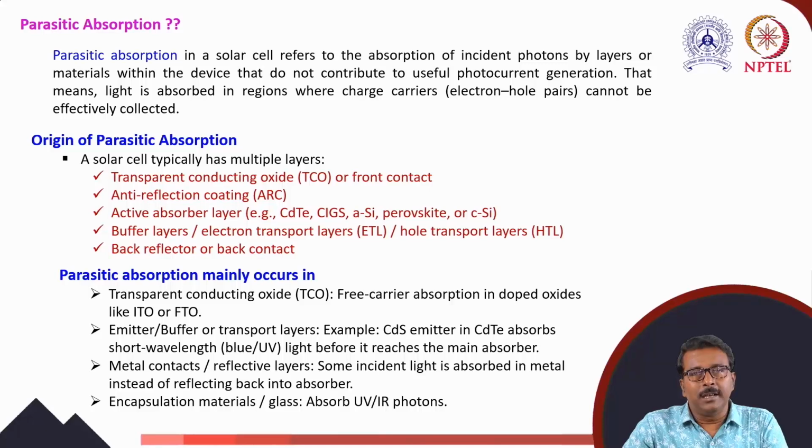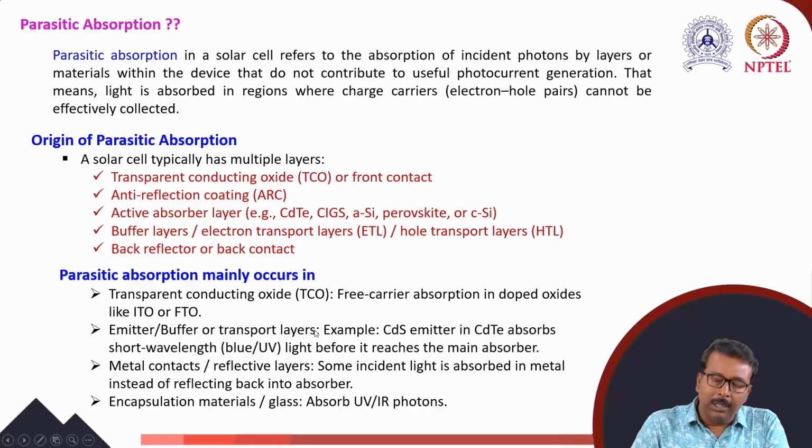For wavelengths outside the transparent region, the light may be absorbed by these layers and generate carriers, but these will not contribute to the photocurrent. Similarly, the emitter or buffer layer.